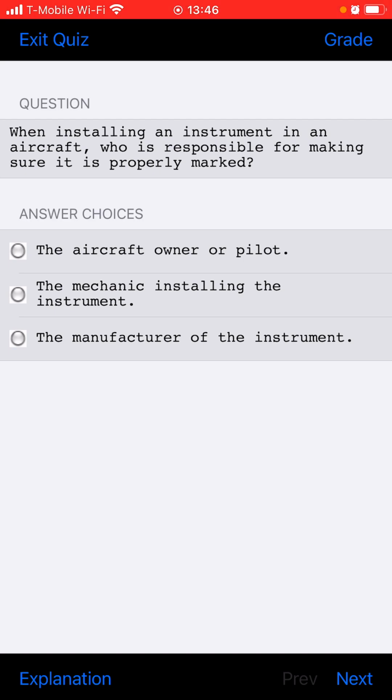Describe the process or mechanism by which a photoelectric smoke detector generates warning of a possible fire. Smoke particles refract light in the detector unit, causing a photoelectric cell to conduct electricity and trigger the alarm.